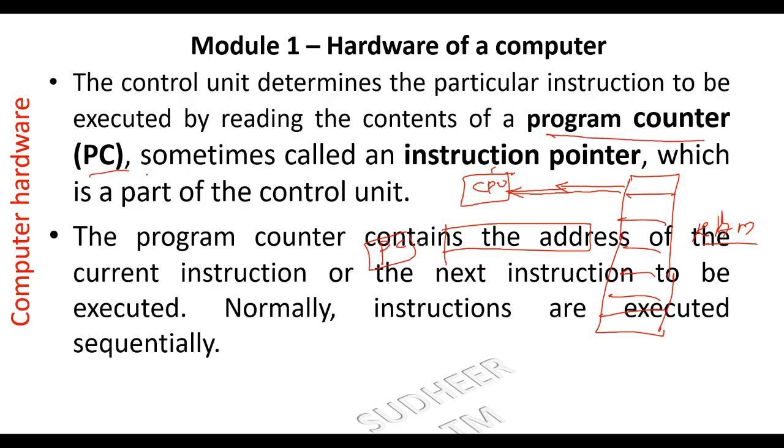Just for understanding, at the beginning the program counter will load with 000, whatever the size of your processor, all zeros. The microprocessor will read whatever data we loaded there. It will go into the CPU, and the control unit will analyze the instruction and, according to this analysis, perform the task. It may read the next data or one more data. Depending upon the task, it will perform that task with the given data, and it may store the data or go to the next instruction to be executed.